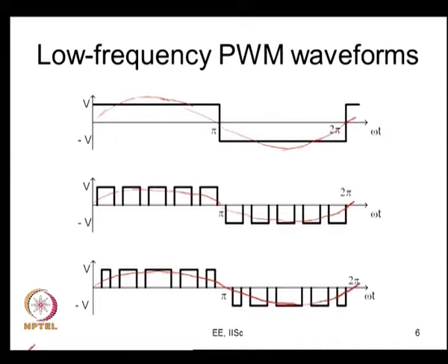You can see that if you look at the sinusoids, it will be very clear that the pulse widths are equal here. Here the pulse widths are modulated in a particular fashion. Incidentally, they are modulated in a sinusoidal fashion here. The width is very high and then low, it varies in a sinusoidal fashion, and you will see that the fifth harmonic could be very high here, for example, whereas in this case that will be pretty low.